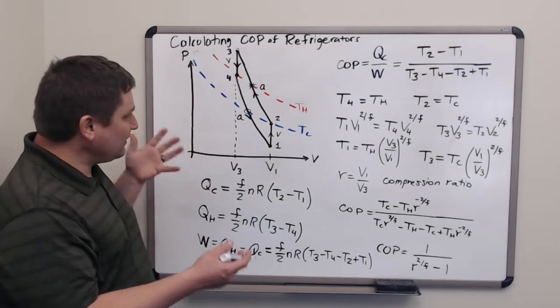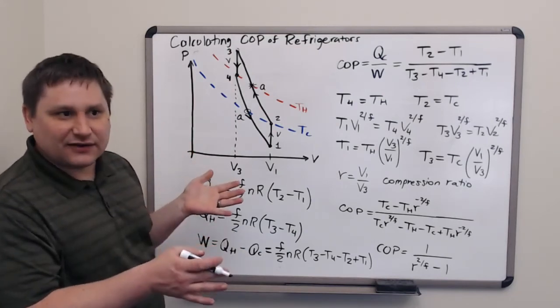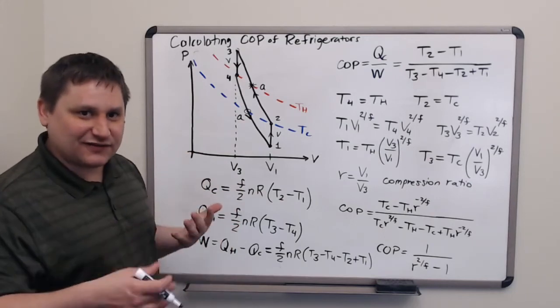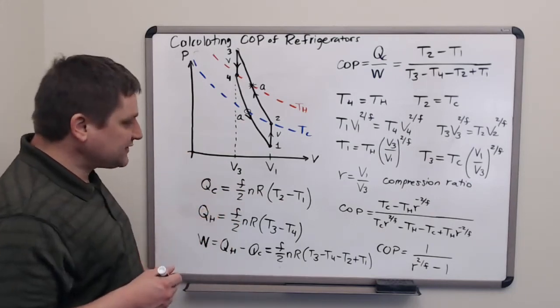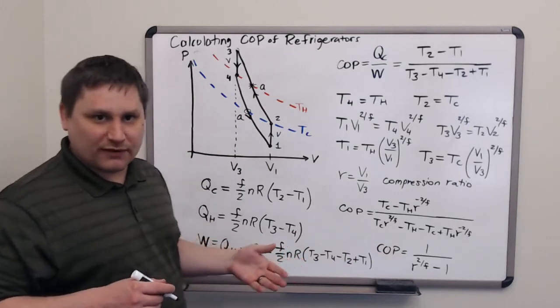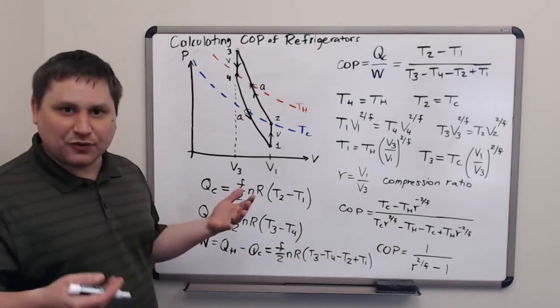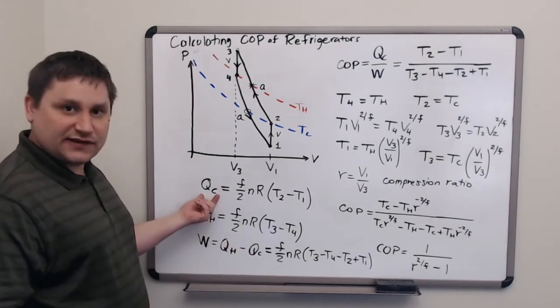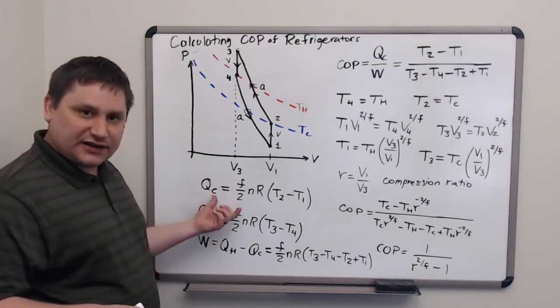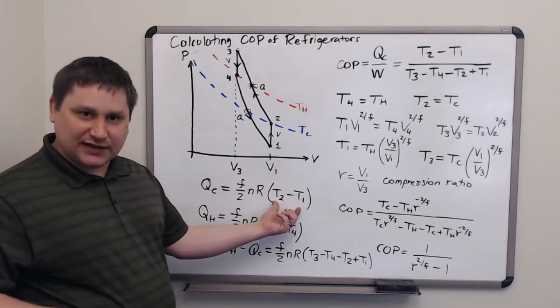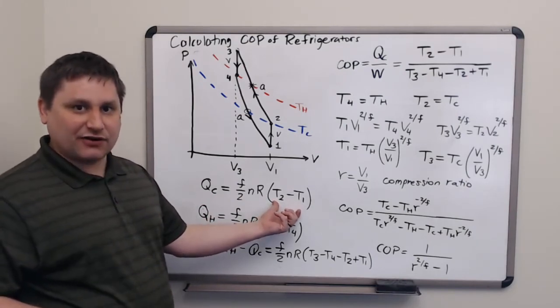The cycle will become just a degenerate back and forth adiabatic compression and expansion, which doesn't really do anything. So in addition to the coefficient of performance, we always also have to look at just the actual value of QC. Now let's write QC in terms of the temperature of the hot reservoir, the temperature of the cold reservoir, and the compression ratio.